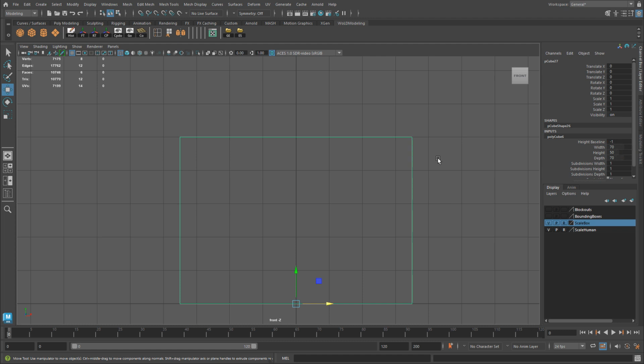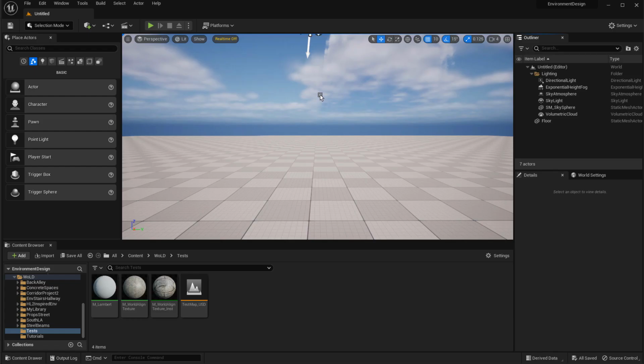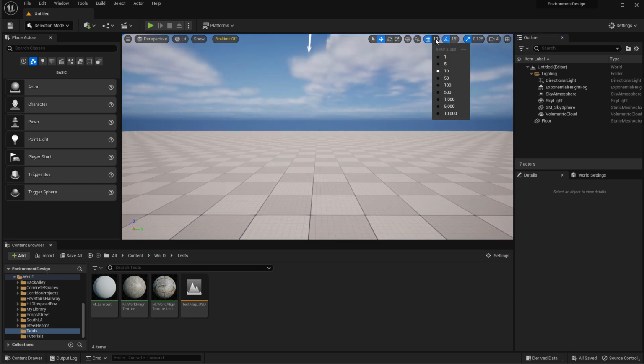And this will be perfect for Unreal Engine 5 because then if I have a crate that's being stacked on top of another, it will be easier to do because it will fit within the 10 unit snap size distance. And yeah, we could lower. So for example, if I go beyond the established boundaries of the crate of these props, I could lower the size back down to 5 or 1 in order to stack them on top. I could also maybe utilize the surface snapping, but it'll make it a lot easier if it's within the grid size that I've established, within the 10 unit grid size.